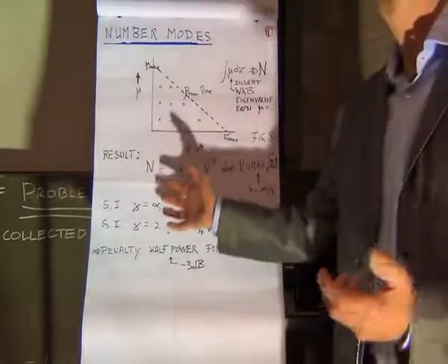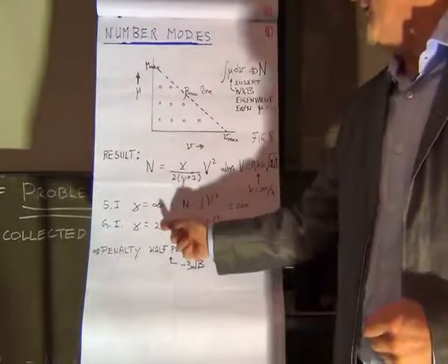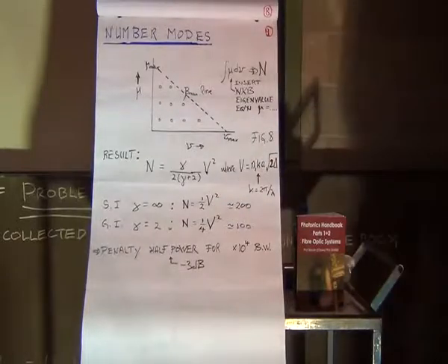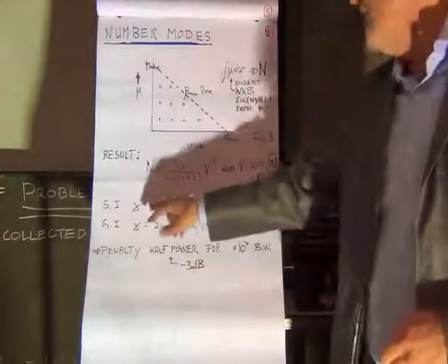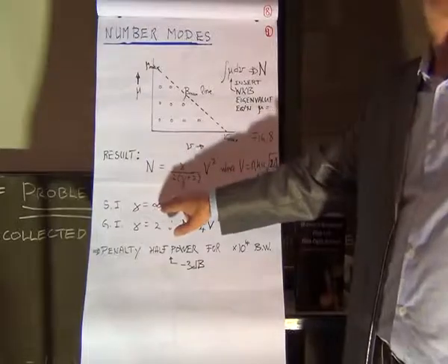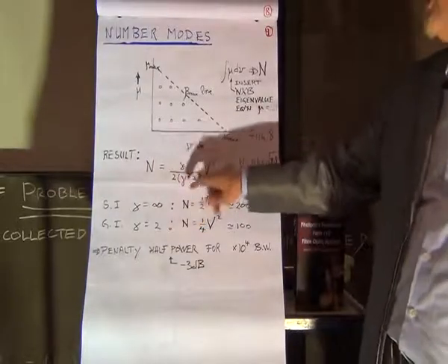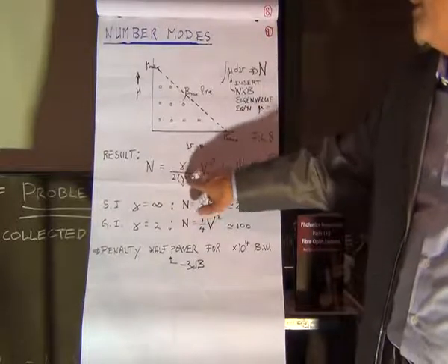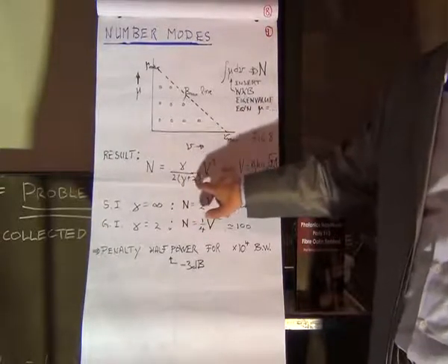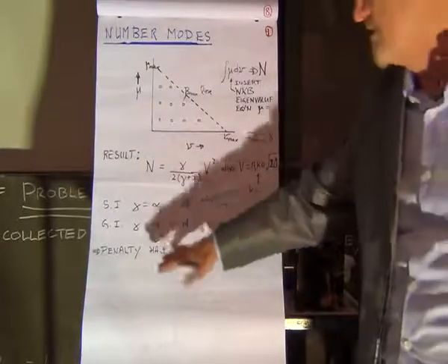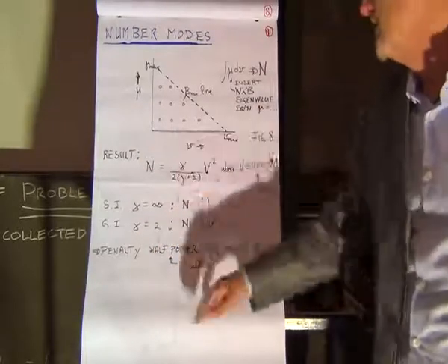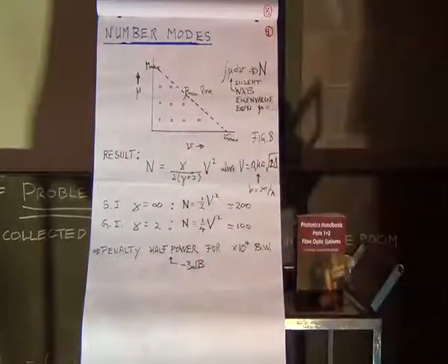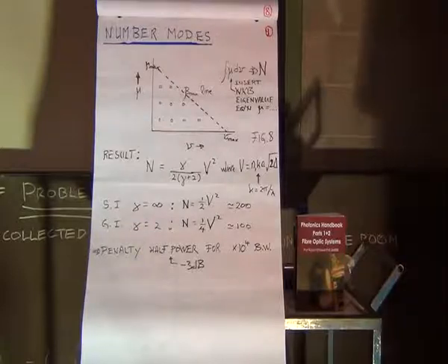Now if you put 2 extremes, infinity and 2, into that equation, you get these interesting results. For a step index fibre, by the way, when you put gamma into infinity, you remember what you do there, you just divide by gamma above and below. So you'll have 1 over, that'll be a 1, plus 2 over gamma, 2 over infinity is naught. Right? So to insert the infinity, that's the way you do it. And put in the 2, you'll just get 2 over 2 into 2 plus 2, a quarter. Very important result.